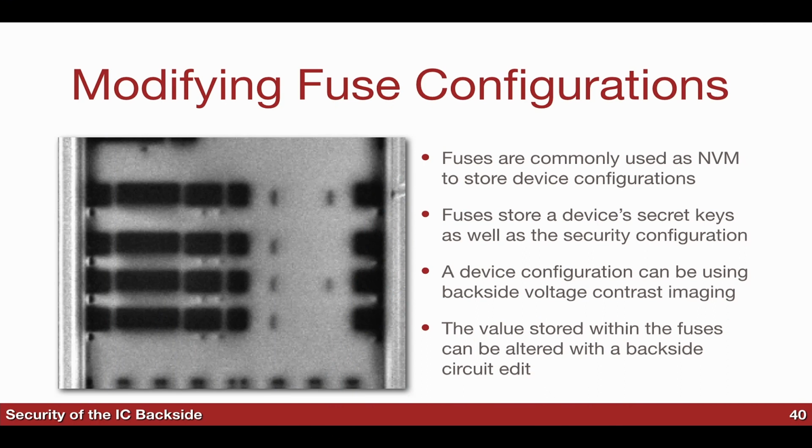And so now this is an area where we have the fuses. You can actually see if the fuse is set or not, because of those dots in both rows. Here you have 8 fuses. The reason for that is the image you get on the FIB is made of secondary electrons, electrons that get reflected off the device and come back into your imaging system. Because you have a fuse and a floating gate, the electrical field is different, and there's some sort of charge there. So you get a different contrast, a different amount of electrons coming back at you, and you can see this.